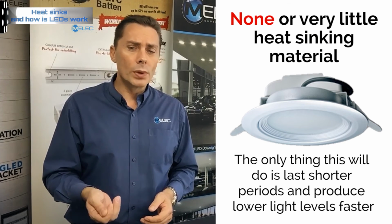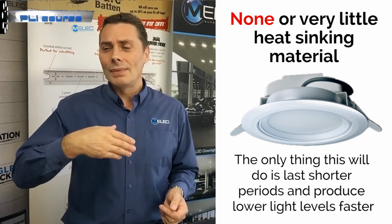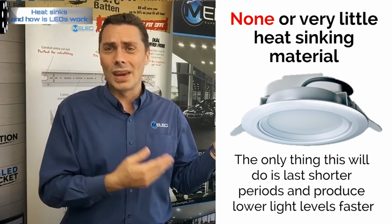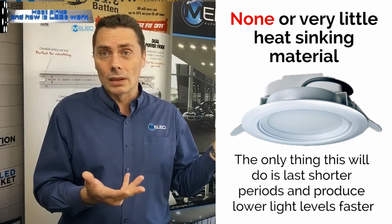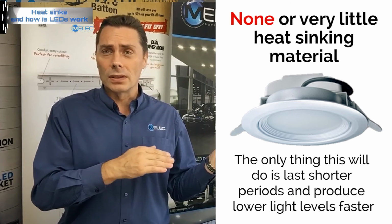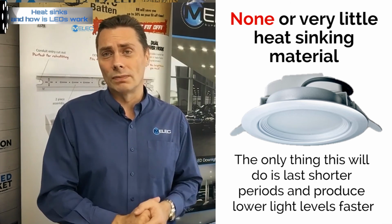Then there are manufacturers and importers who look for methods of cutting costs, and they come out with ideas like this one here, for example. It doesn't have any heat dispersement whatsoever, or very little. The only thing this is going to do is shorten the lifespan of the fitting itself, so you're going to have to replace it, and the light levels will reduce much quicker and faster.